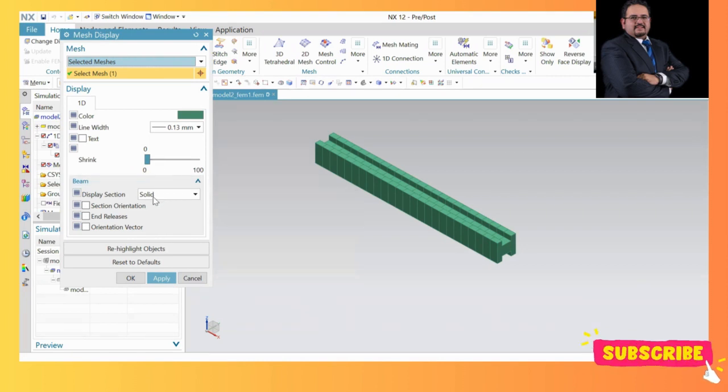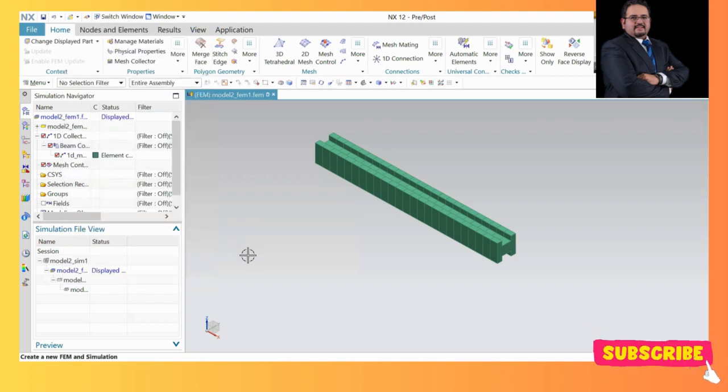Sometimes in order to facilitate picking, because we need to pick nodes when we fix the nodes and when we apply loads, sometimes it gives you trouble when you are picking. So the recommendation is that you keep it off. But before this, there is one problem here right now. If you see the system X and Z system I have assigned, right? Generally Z is the vertical one. So your beam is 90-degree tilted right now, right? It needs to flip up so it can go in the Z direction.